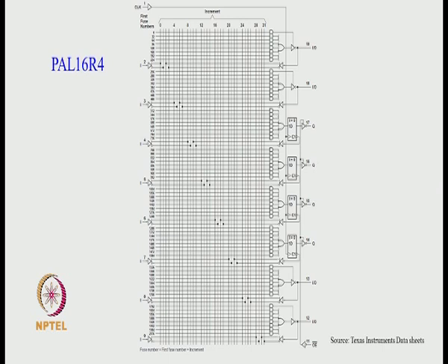It is even possible that you can implement an FSM. If you remember, an FSM is nothing but a counter with an output decoder. You have next state logic, you have the present state. Now you know that what the FSM requires is an output logic which decodes the present state and input. Now you take this section where all the present state, Q0, Q1, Q2, Q3, is available. So in principle you can form an output which is a decode of Q3, Q2, Q1, Q0, and if it's a Mealy output, you have various inputs, you can give input and still decode. You have the inputs available because all vertical lines are available here, and the present states are available here. So you can form an output logic here and try to implement an FSM.